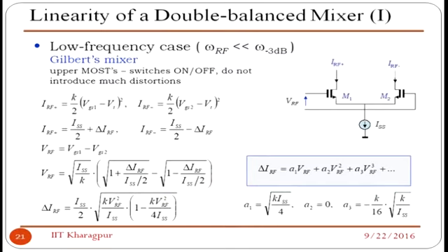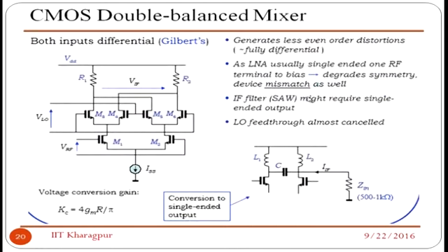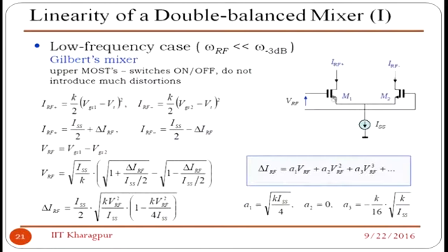But now coming into this, suppose this is my RF. Remember, I am talking about the analysis of that. So RF, this is the switching block. The gain is essentially coming from this RF block. If you look at here, for the M1 and M2 transistors, IRF plus is mu n Cox WL by 2, that is K by 2, times VGS1 minus VT square, and IRF minus like that. So if there is a change in current, say delta IRF, and this is a balanced structure, ISS will be divided by 2. So ISS divided by 2, and this one is ISS divided by 2 minus delta IRF.